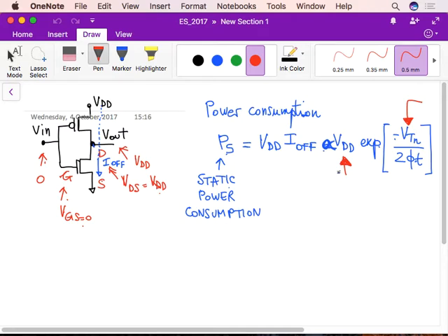And the reason why the reduction of the threshold voltage has virtually stopped, technology after technology, is exactly the fact expressed by this formula: if we reduce a little bit more the threshold voltage, we increase too much the static power consumption.